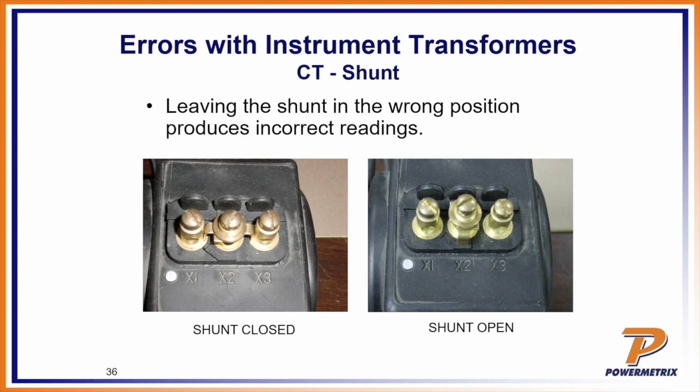Now, why do you need to be careful of that? Well, you already know. Whenever you're going to that CT, before you do any work, before you pull anything, for safety's sake, not only are you wearing all your PPE, but you need to make sure that shunt is closed so that you don't have an accident.